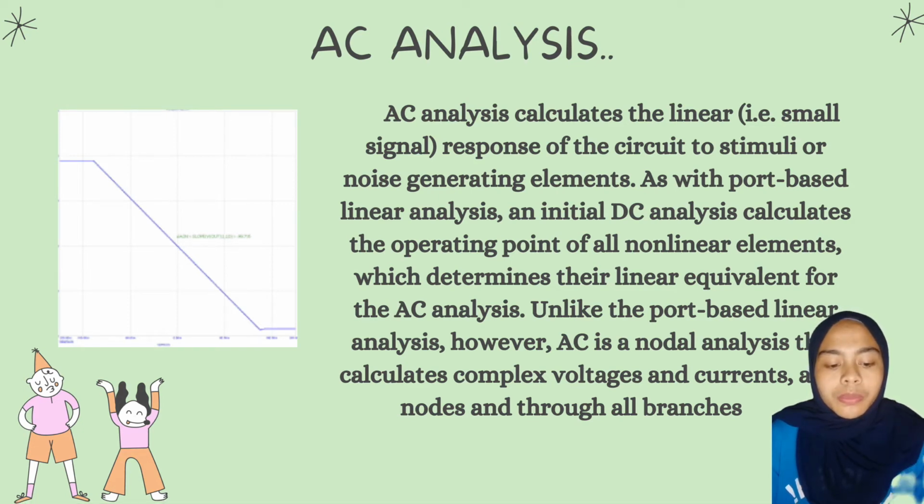Unlike the port-based linear analysis, however, AC is a nodal analysis that calculates complex voltage and current at all the nodes and throughout all of SPICE.